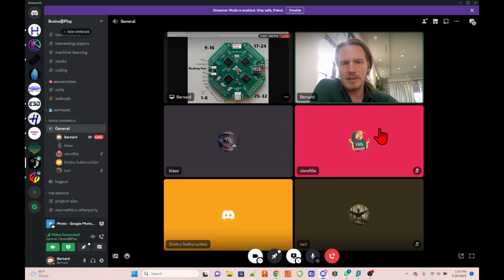So this pin here can be 3 or 5 volts, depending on the tolerance of the other device you're connecting this to. In my case, I'm using a 5 volt application here, and I'm powering it. I just soldered a wire from the power supply here, and that wire goes to 3.3 and to ground. Then I have my optical components here, which require 5 volts.